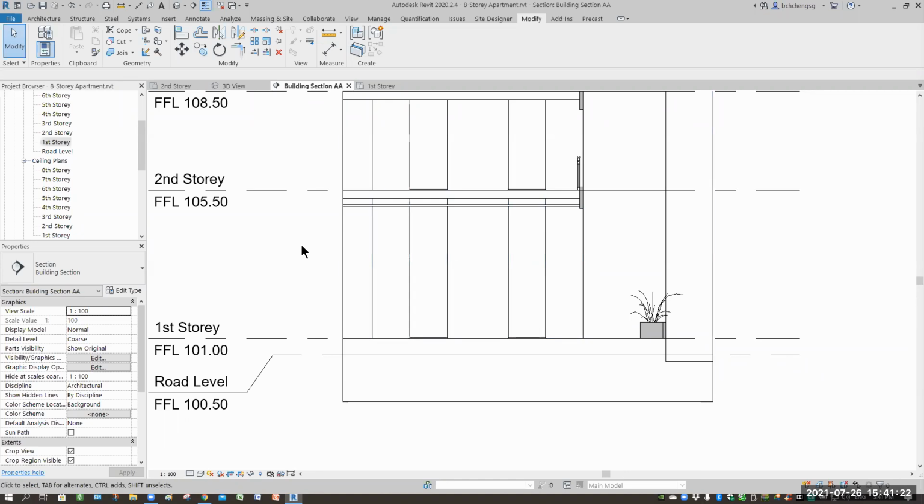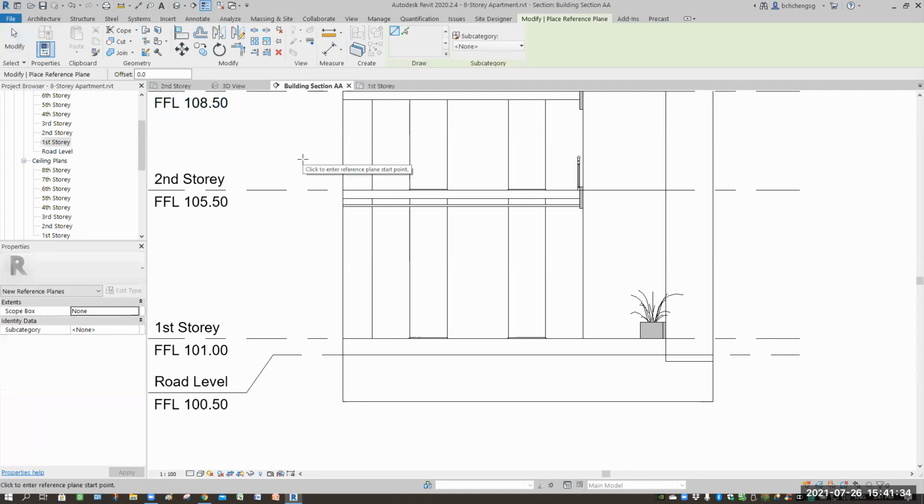If you're not sure where the 2.6 is, very simple. Temporarily, you will offset the height, which is RP. You know what's RP, right? Reference plane. So select pick line, offset, let's say 2.6. This is the clear opening height for the first story lift. So it should be around this height. Okay, so 2.6 is actually considered quite high already.